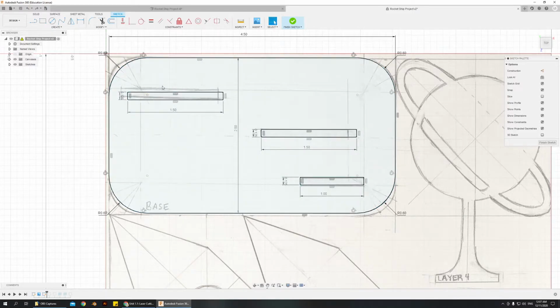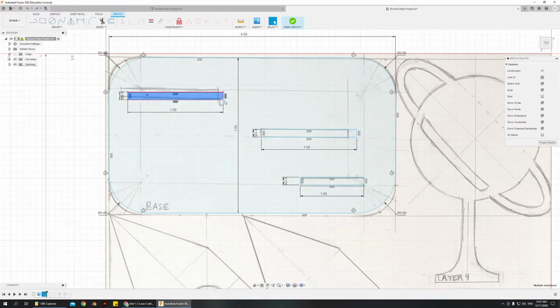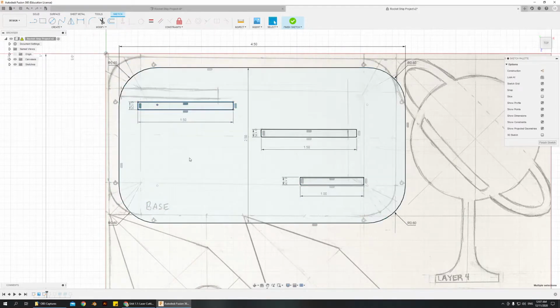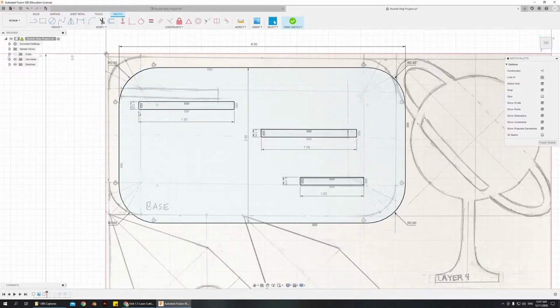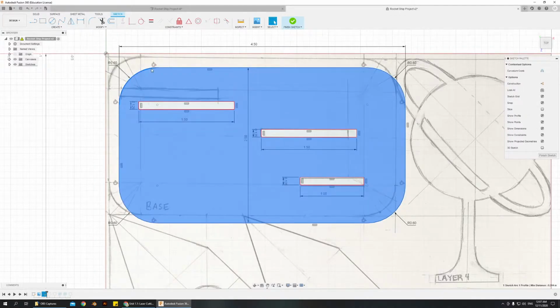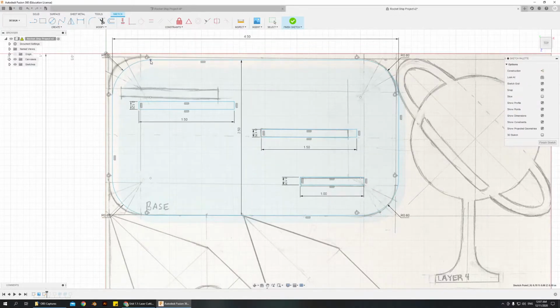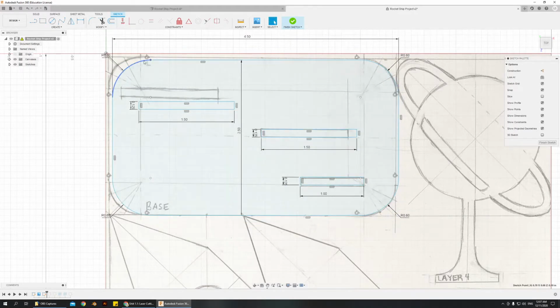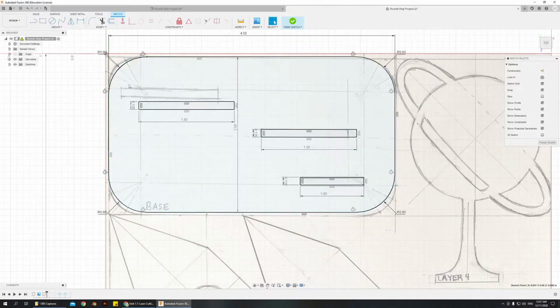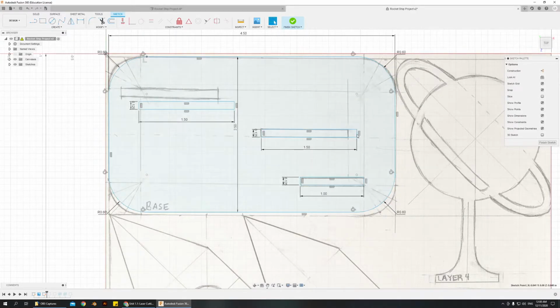You should be able to select just this part though. How come I can't move that? There, okay. If I select this face and then I can grab the point there. There we go. Now, we want to move this guy again. And the other thing you could do is if you wanted everything constrained, you could actually say that the distance from here to here matters. You can actually measure and lock that distance in.